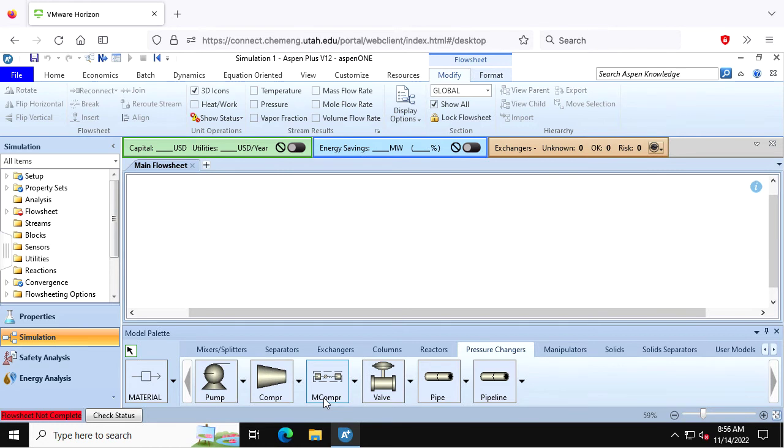So you maybe increase it from 1 to 4 atmospheres, so a compression ratio of 4, and already the gas is heated up quite a lot there. Then you run it through a heat exchanger to cool the gas back down. Then you go from 4 to 16, and then maybe 16 to 64, and then eventually to 100, whatever. But after each of these stages, you have an intercooler to cool things back down, which is good because a really, really hot gas is not very dense, and the efficiency of pumping or compressing improves the more dense the material is. Okay, so that's a multi-stage compressor.